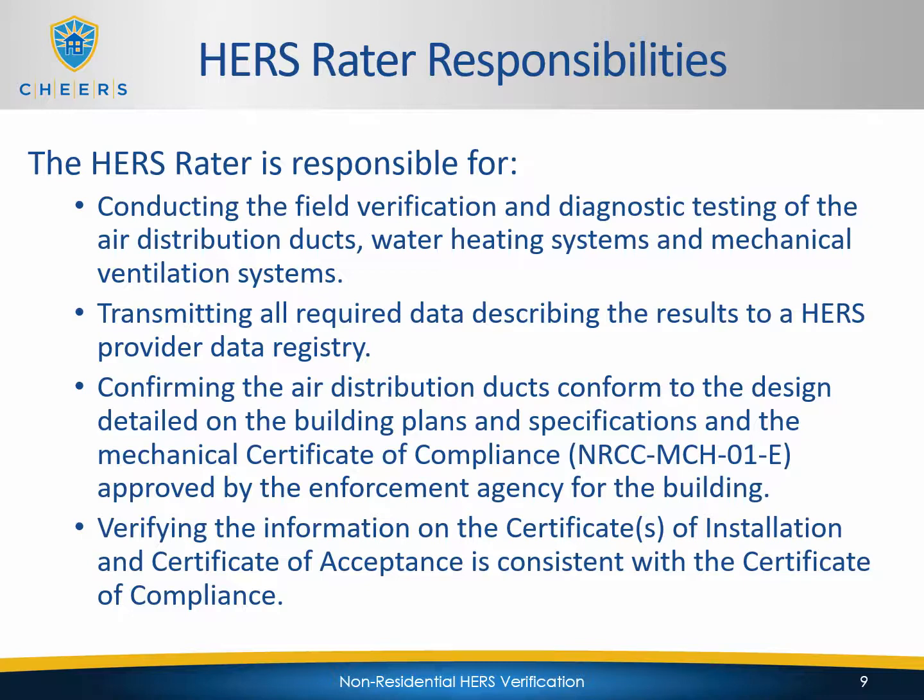So if you look at the one that's listed here, the NRCC MEC 01, if we look at the first four letters there, NR is non-residential. This first C is for certificate of, and then the fourth letter there on this particular one is a certificate of compliance. So you'll see an NRCC, NRCI, NRCA, and NRCV, and those all are directly associated with compliance, installation, acceptance, and verification.